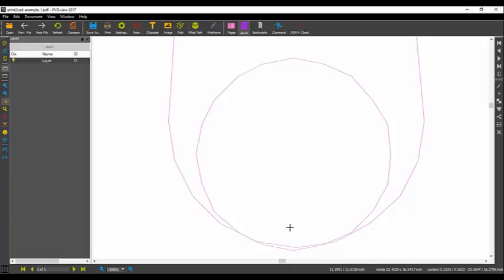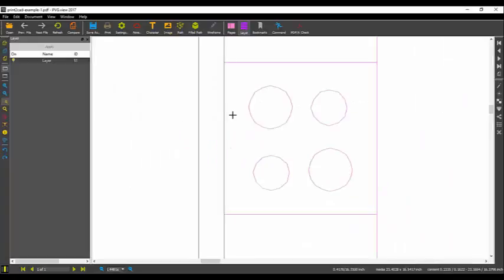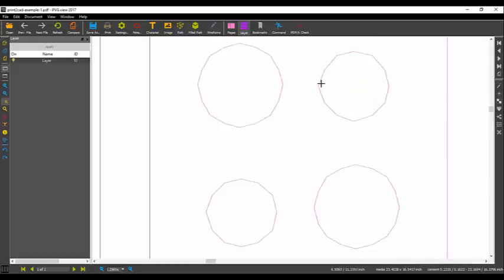300 DPI, dots per inch, is maybe enough for a plotter, maybe enough for print, electronic print too, but is absolutely not enough for CAD systems. And this is the reason that now what you see is a circle in terrible quality. Why? Because this is not a circle, this is a polyline, but this polyline represents a circle, and this polyline is here, so you see these DPI points. And if you zoom, for example, into these circles, you will see these circles are in 300 DPI points.